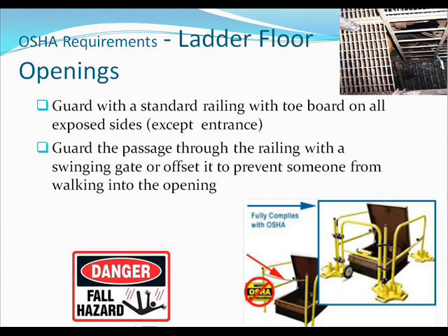Ladder floor openings. Guard with standard railing with toe board on all exposed sides except the entrance. Guard the passage through the railing with a swinging gate or offset it to prevent someone from walking into the opening.